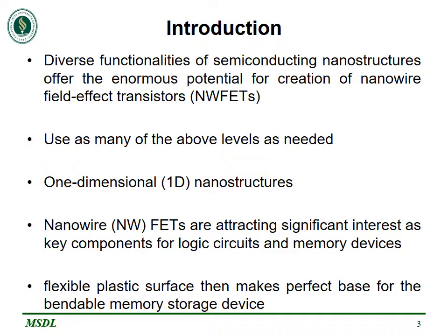In particular, nanowire FETs are attracting significant interest as a key component for logic circuits and memory devices because of the ability to precisely modulate channel conductance and threshold voltages of FETs through the surface engineering of a nanowire. This controllability provides a promising route to a range of functionalized memory devices based on a simple low temperature fabrication process that in turn allows for an application on flexible plastic substrate, and this flexible plastic surface then makes a perfect base for bendable memory storage devices.